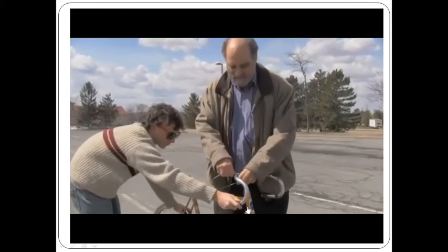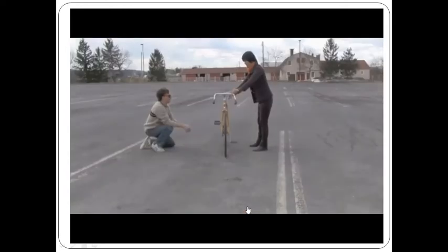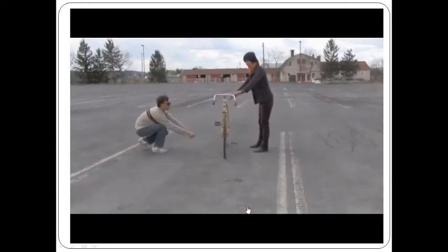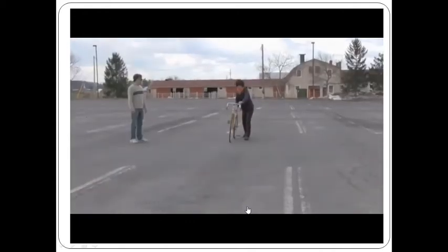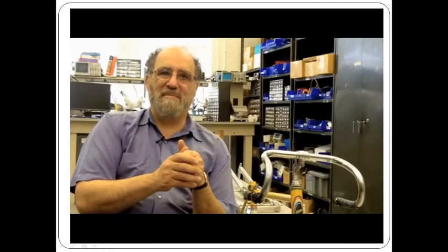Bicycles are amazing that you can balance them. Somehow, on just 2 narrow wheels, you can keep them upright. And you can only keep them upright when they're moving. What's well known about bicycle balance is that the major effect is that steering is what gives you balance. If you lock the wheels of a bicycle so it can't steer, the angular momentum of the wheels contributes exactly nothing to bicycle stability, and it falls over when it's moving forwards exactly the same way it falls over when it's stationary.